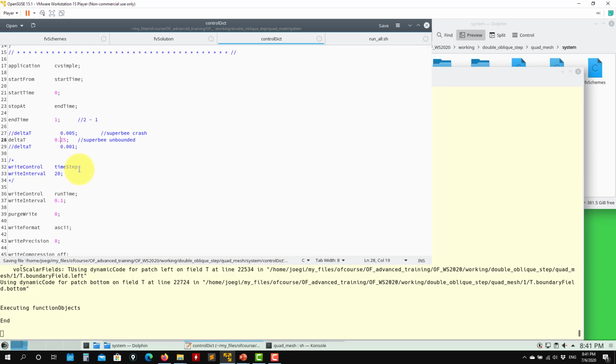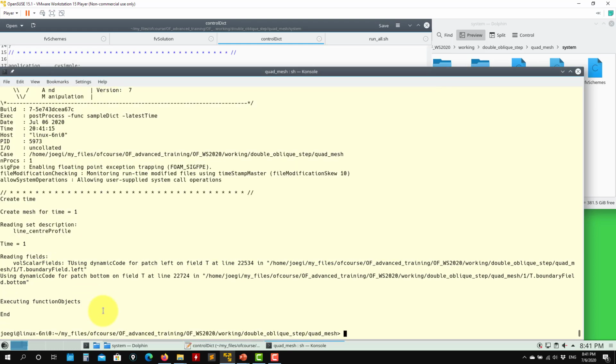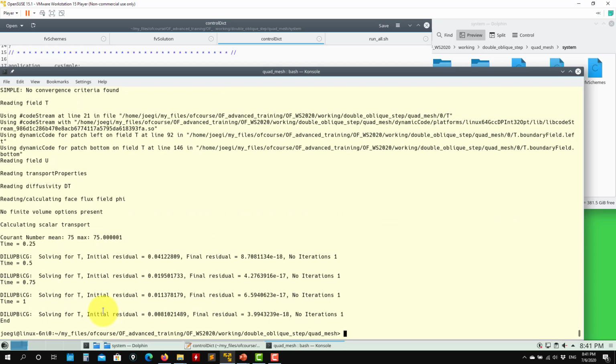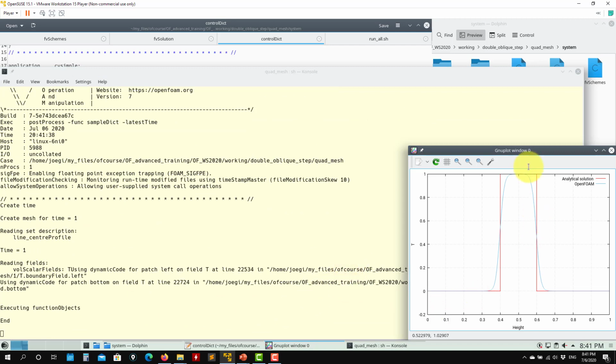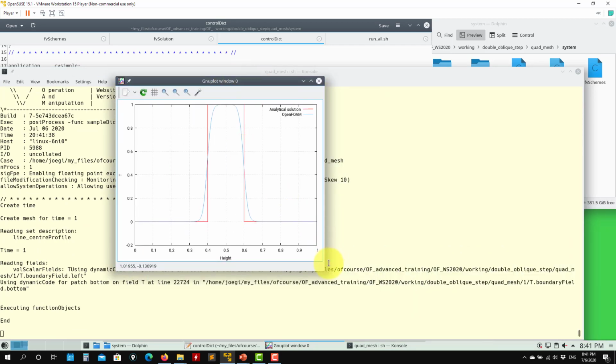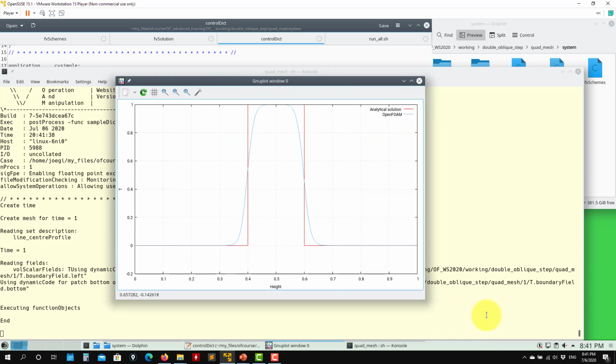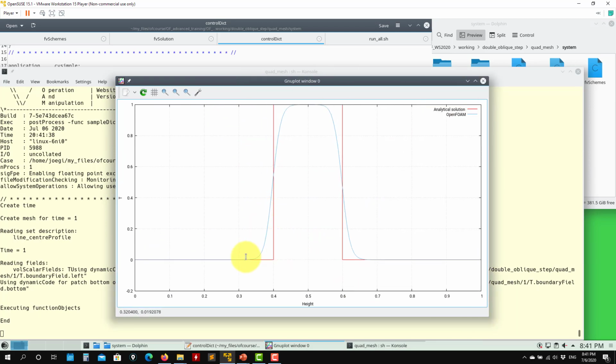As you go here with a very large time step, where the previous cases were giving problems, or were iterating but the solution was very unbounded, let's see what we have here when we do the sampling. See that it is working. And probably contrary to what you might think, that a larger time step will be less accurate, here it seems to be getting more accurate.